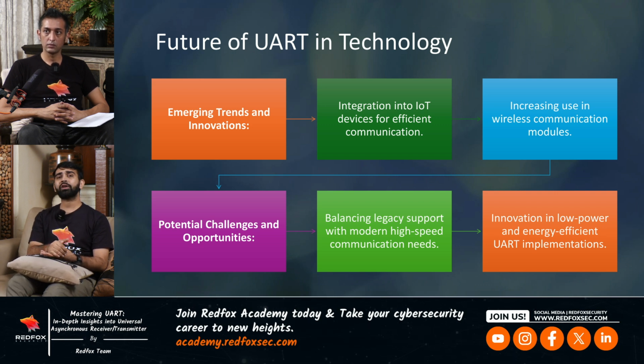Also, if you look at drones for national security or other uses, they keep these interfaces for troubleshooting. RF challenges are already there because of software defined radio, so they are securing that more and more. But in the protocol part they keep the test pins, UART and JTAG, mostly untagged.